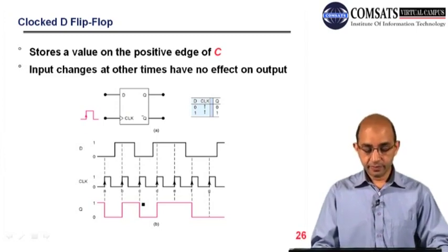And here again we have to look at D. D is low, so there will be a toggle, or transition from high to low, because Q has to follow D, and then Q will remain in the low state till the next active edge or rising edge.